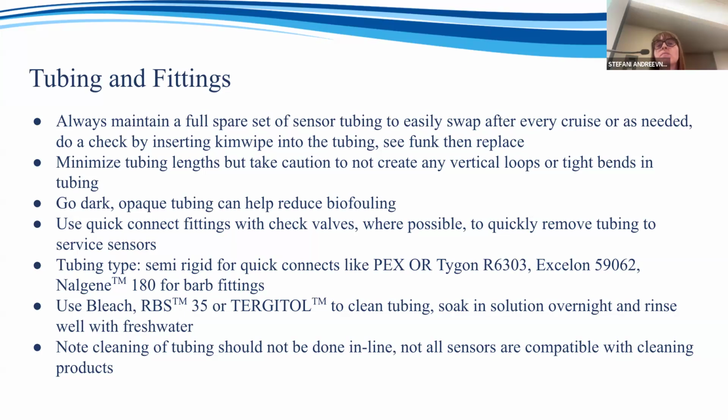Minimize tubing lengths as much as possible, right? You don't want to create any vertical loops. You don't want tight bends, keep it simple. Go dark and opaque when you can. It'll help reduce biofouling.